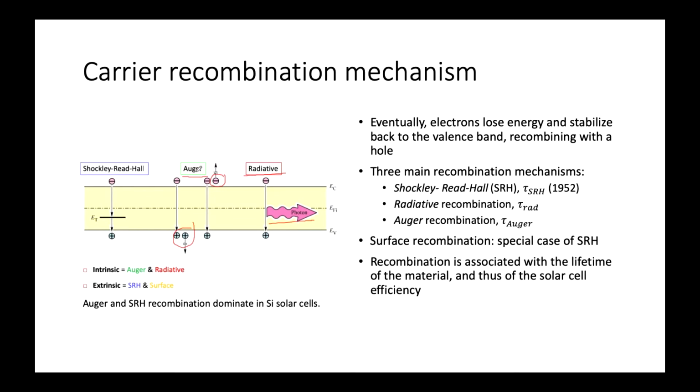Now, in the case of extrinsic recombination, the decay does not occur directly via band-to-band transition, but by an electron transition via a defect center with an energy level in the band gap. This process is commonly known as Shockley-Read-Hall recombination. Shockley, Read, and Hall formulated this theory of recombination in 1952 from statistical considerations, and this theory is the basis of lifetime spectroscopy.